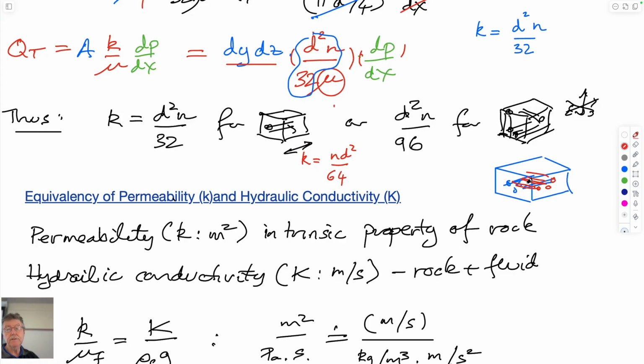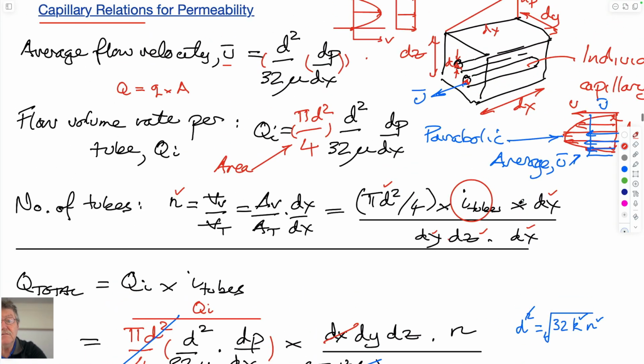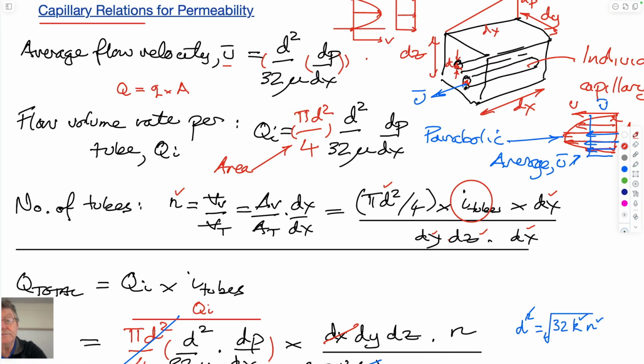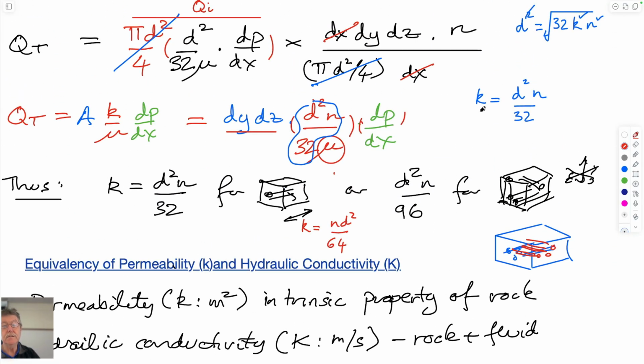That is because we've divided the porosity between the capillaries which are flowing in the x direction and also the capillaries flowing in this particular case, the y direction. So that volume is distributed in those two sets, but we're only getting flow out of one of them, and so it cuts the permeability in half.